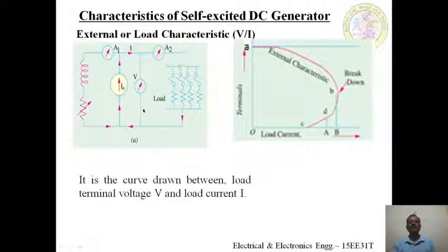Before loading the generator, first, as we discussed already, the generator has to build up its rated no load terminal voltage.